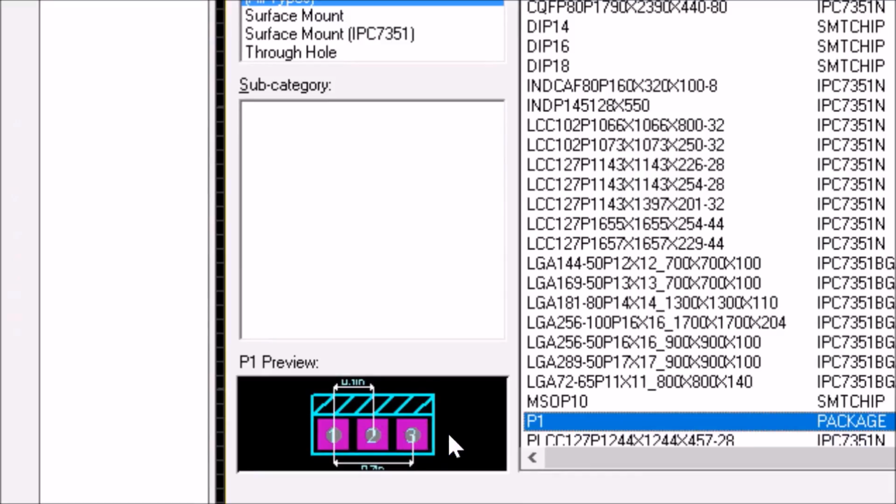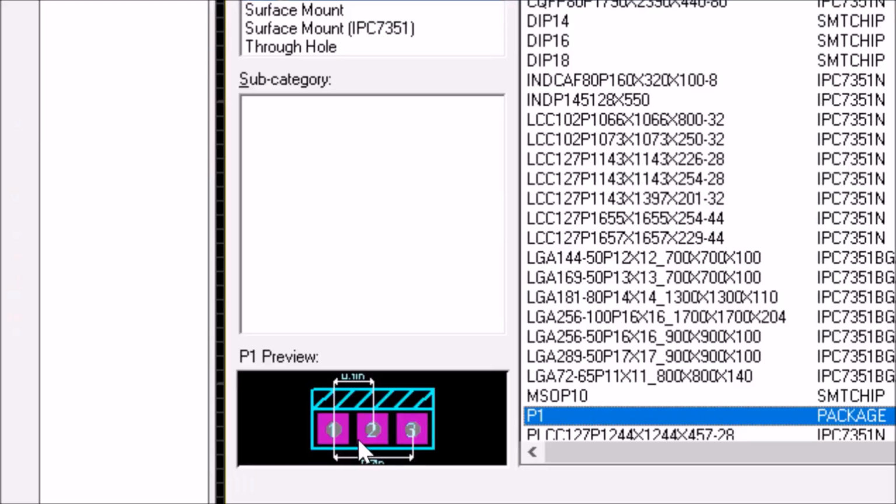So this is for my regulator. So guys, you should be careful when you're choosing this. Maybe you can have a MOSFET, and yeah, MOSFET and this guy all really look similar in terms of the leg, in terms of the pads and every other thing. But MOSFET has a much bigger gap. Yeah, you have a much bigger gap, and it really shows that both of them are not actually the same. In case you're doing that, that's why I say you have to buy these and keep them as you are choosing them. But if you keep practicing every day, you're gonna make sure you know the ones you're using every time, and it will just be much easier for you.